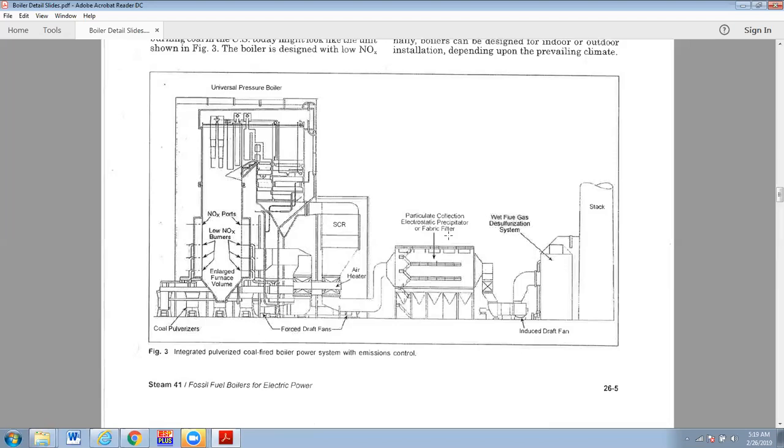The bigger units are electrostatic precipitators. We'll talk a little more about those. How those operate is they have these electrodes, long electrode wires, and they induce a significantly high voltage. And the voltage basically attracts the ash particles. There's a charging mechanism somehow in there. And anyway,